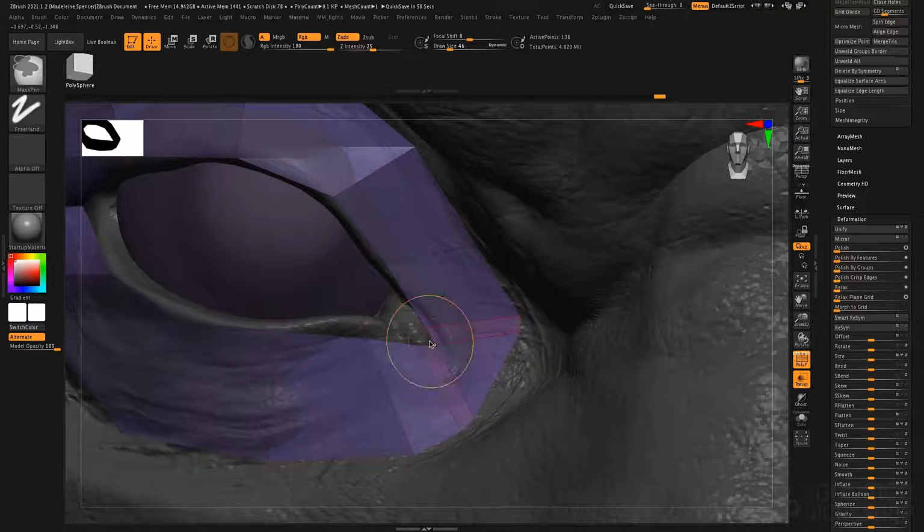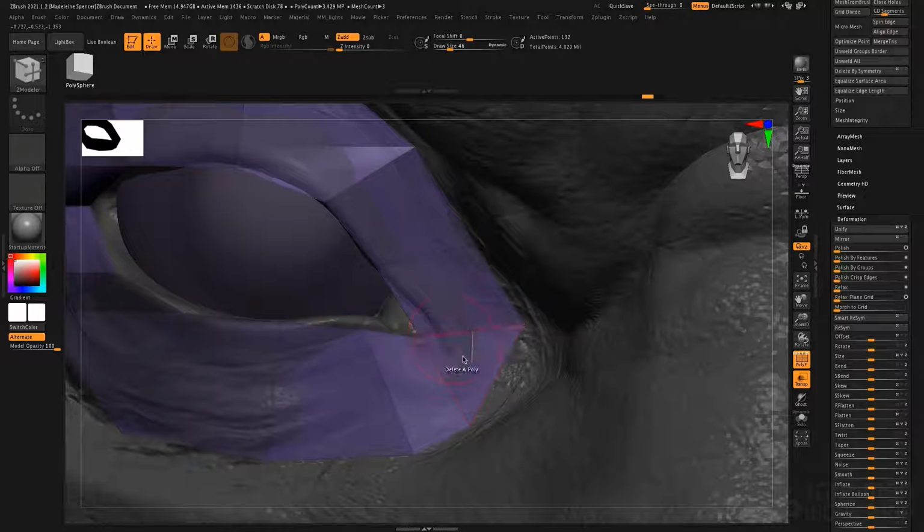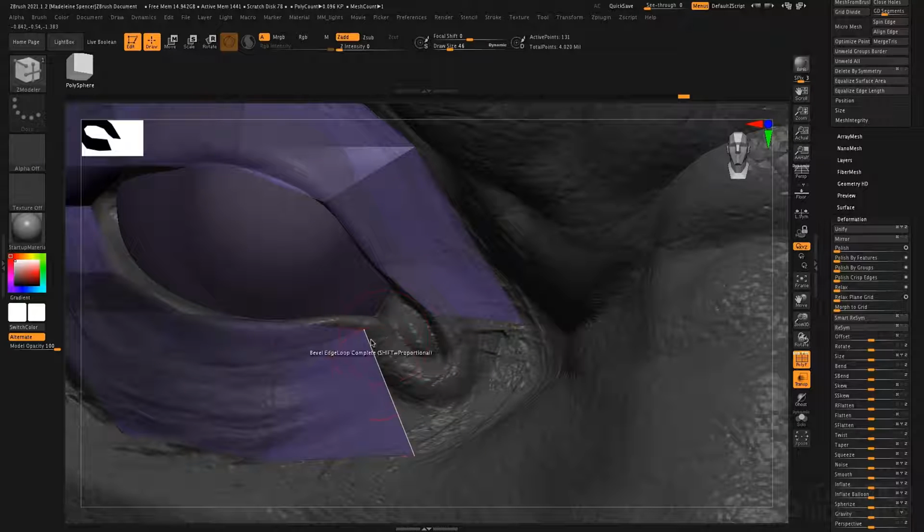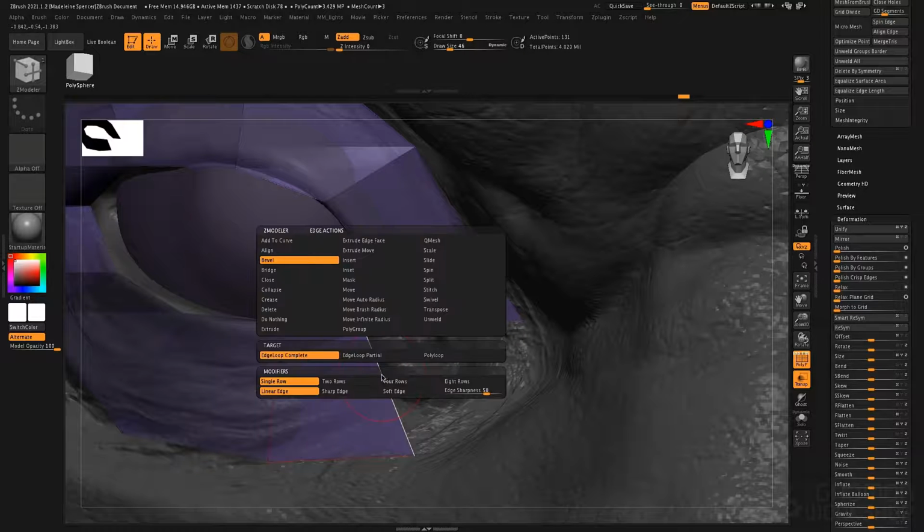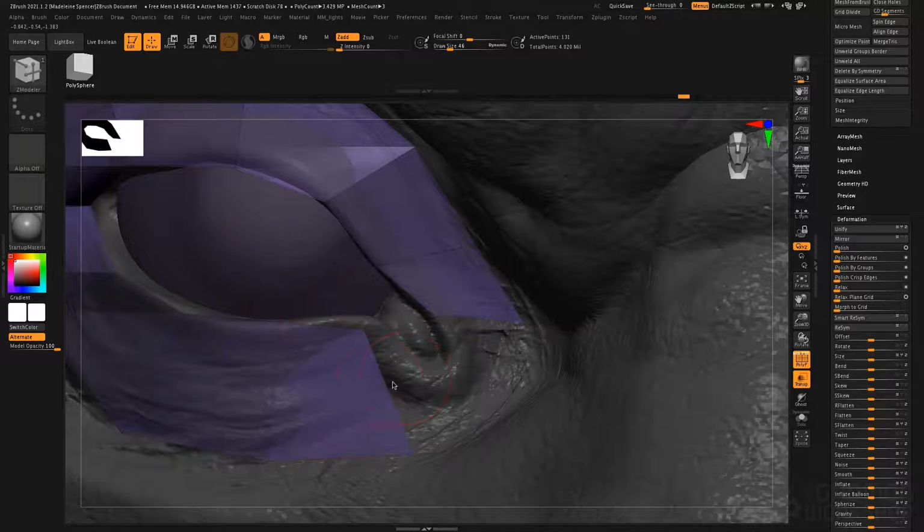It doesn't really quite solve the problem though, so the best thing to probably do in this case is to mouse over this face, delete it, delete this one, grab this point and go to move, make sure I'm over the point, and move this point back up here, and then I'll just extrude this face. So let's go ahead and extrude, bring this down, bring this point up here, make sure that we're on the point, and then I'll just bring this up until both of these merge together, and I'll just manually grab this point and drag it up to there, and now we've got a nice continuous quad.